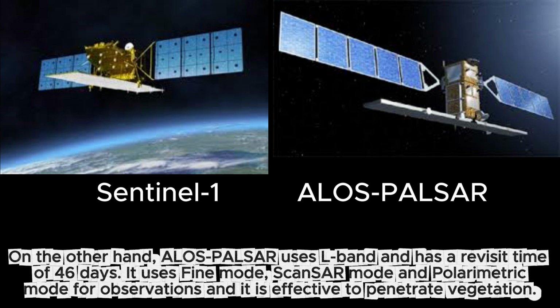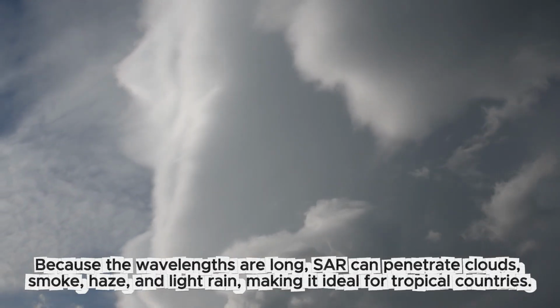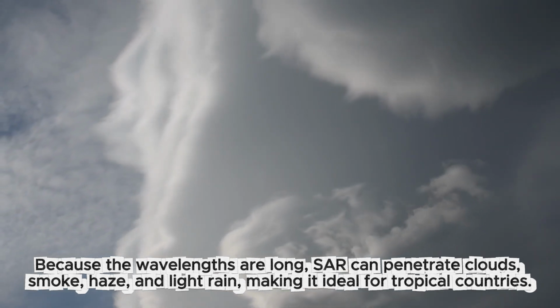On the other hand, ALOS PALSAR uses L-band and has a revisit time of 46 days. It uses fine mode, ScanSAR mode, and polarimetric mode for observations and is effective at penetrating vegetation. X-band has higher resolution but less penetration. Because the wavelengths are long, SAR can penetrate clouds, smoke, haze, and light rain, making it ideal for tropical countries.